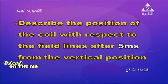Describe the position. This is a very interesting and intelligent question. Describe the position of the coil with respect to the field lines after 5 milliseconds from the vertical position. Your attention please, we are starting from the vertical position. So the instantaneous EMF will be equal to EMF maximum times sine of the angle. If we are starting from the horizontal, we should use cosine of the angle.